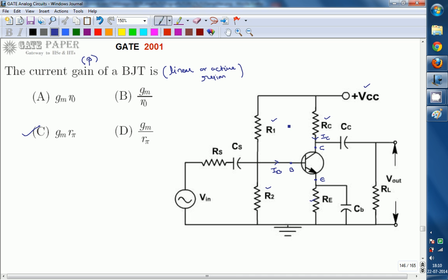Now when the transistor is in the active region, if you apply an AC signal like Vin, it is going to be superimposed on these voltages, so the current flowing previously will be modified, it will change accordingly with the input. Because of this input which superimposes on the previous voltages and currents, you will get an extra current, a small signal current, remember that. AC implies small signal voltage, and because of that you will get small signal currents.